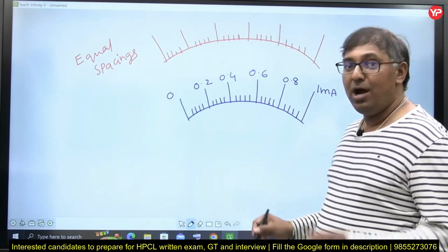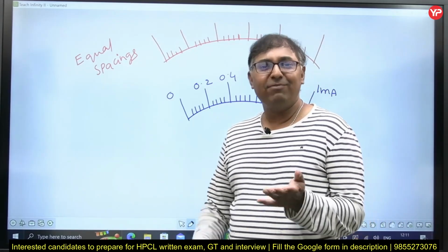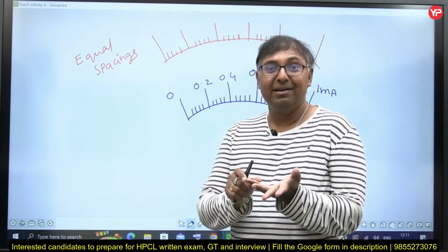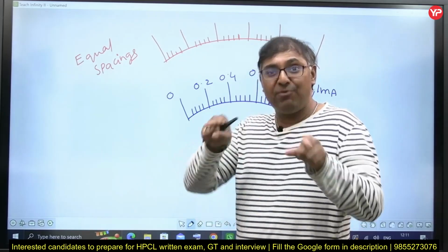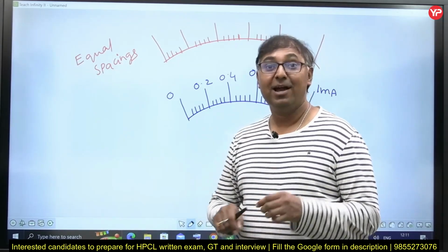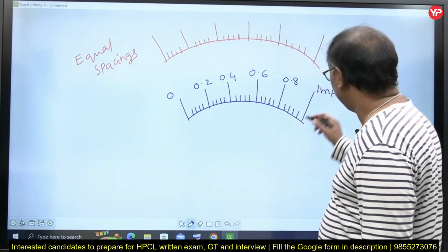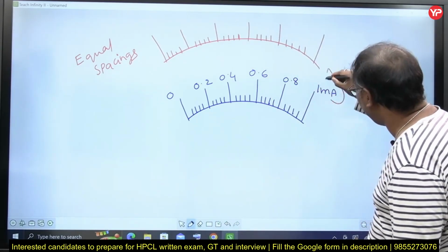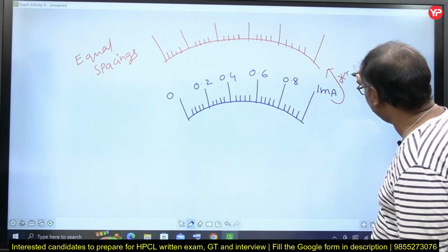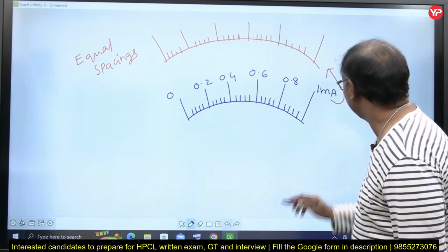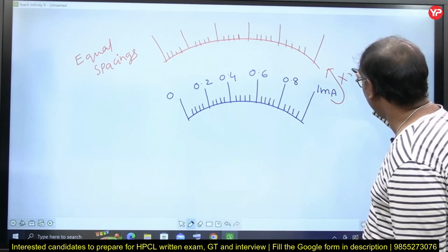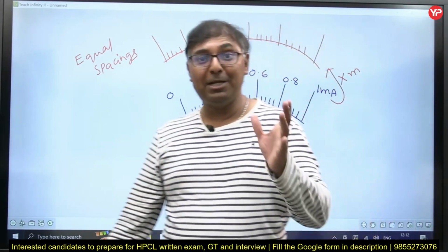So now, how do we measure 10 milliamperes? When I have a 1 milliampere meter, when the scale is designed or manufactured for the 1 milliampere range, how is 10 milliamps indicated? The available scale has to be multiplied with M. What is M, sir? Multiplication factor.